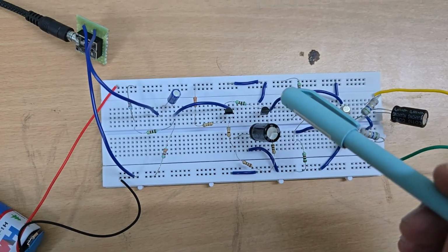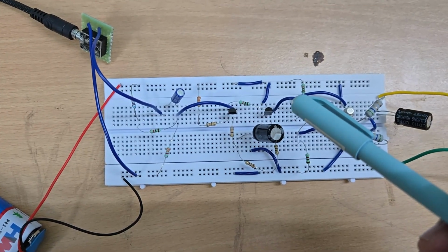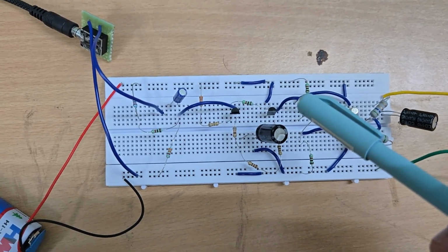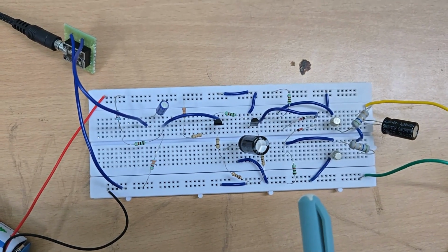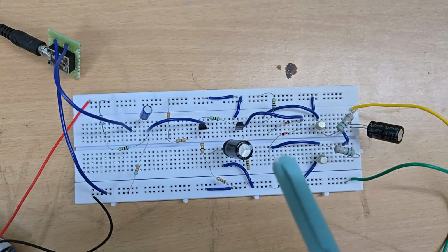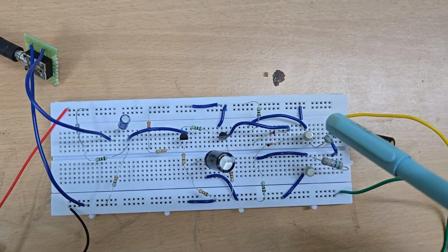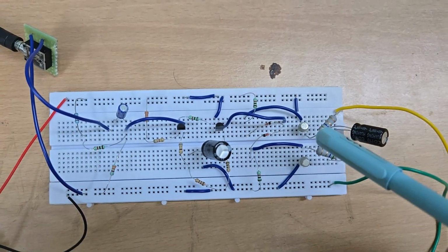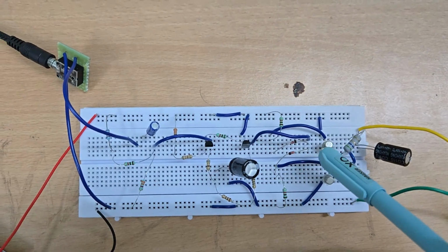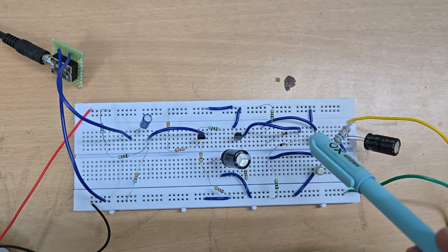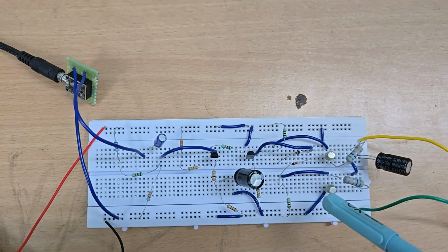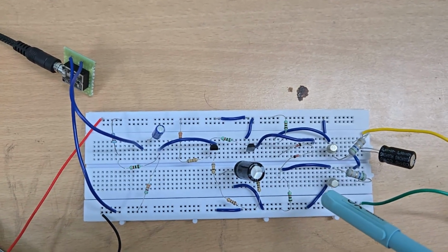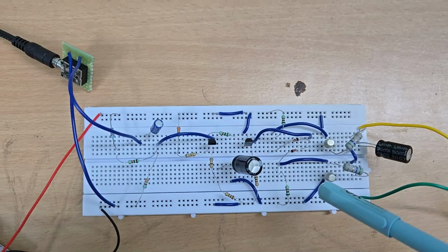The gain of this transistor is unity, but it is used for matching the impedance to the output. Then the next stage is class AB driver, which consists of these 2 transistors. So this transistor is 2N2222 and the other one is 2N2907, which is an NPN and PNP pair.